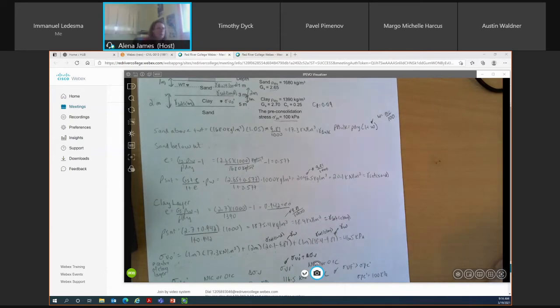One thing to note when you're doing calculations, the void ratio of a sand material is in the 0.5 to 0.65 range. So when you're calculating your void ratio for sand, if you're up around 1, double check your calculations. There's something that's not right. Or if you're above 1 for sand, like you've calculated 1.5, you probably forgot to subtract 1. So you should be looking for something in the 0.5 to 0.6 ballpark for sand.